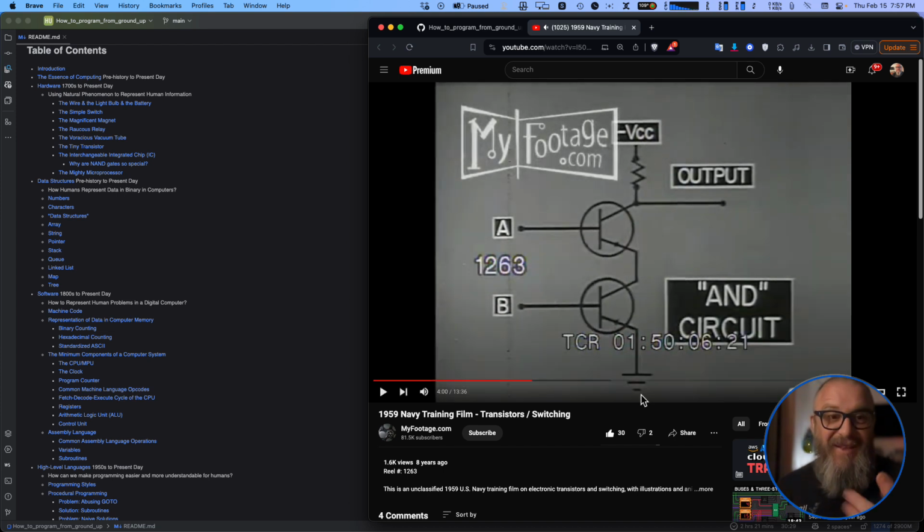So in this case, a 0 isn't lack of current. A 0 is negative current. So positive current, negative current, just to make sure it knows, and it's not floating around. We'll talk about floating around if it's unhooked in digital electronics. They have to actually go to ground, or be wired to the negative or wired to the positive. We don't want it floating around. It can cause strange, undesired conditions.